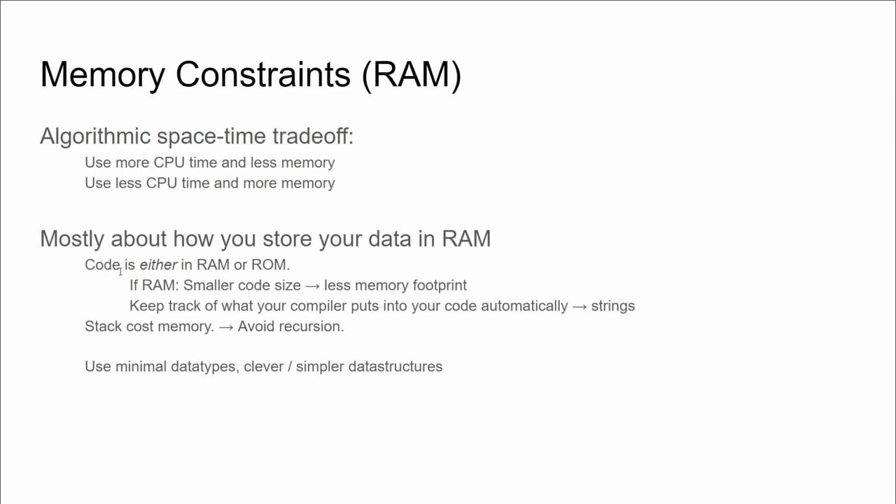Also, recursion. It's an academic endeavor that's interesting, but as things often go in real life, less useful. Recursion typically adds a stack cost, and that stack cost can be quite substantial, and therefore not an option in a RAM-constrained environment. I would generally avoid recursion in any industry code I ever review.